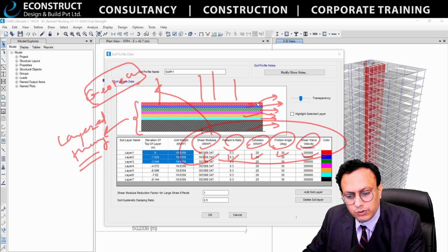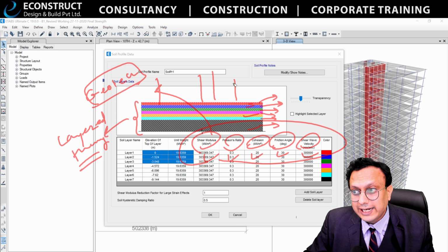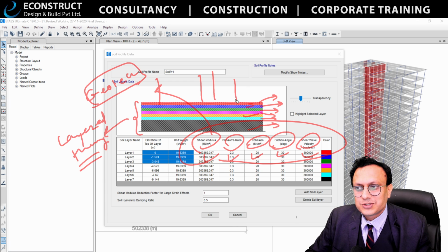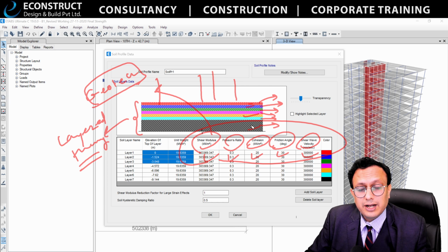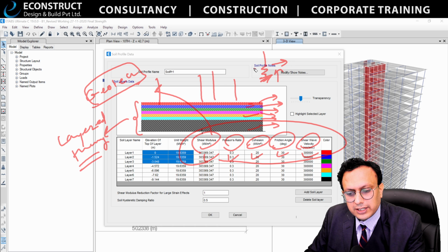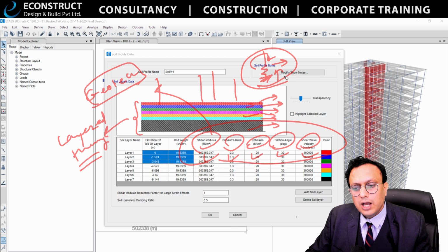The different values of the shear wave velocity will be attached to the foundation system, and you might be knowing that the soil has very non-linear and non-predictable behavior, and it is very difficult for the consultants to add all the values only as a spring constant in the vertical direction, horizontal direction, rotations and all. It is impossible for any consultant to carry or to give these values.